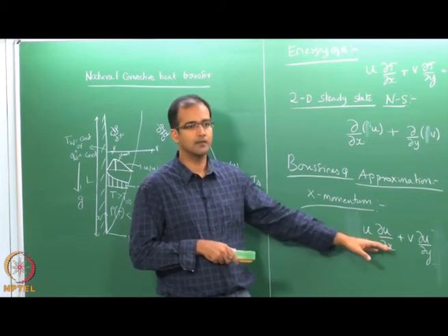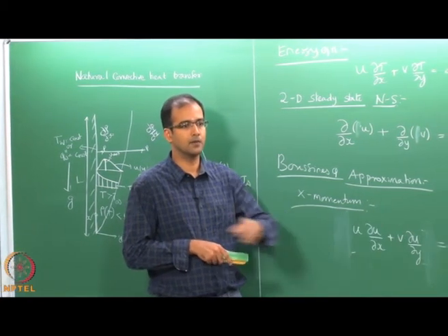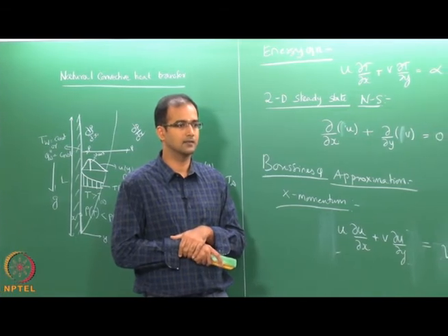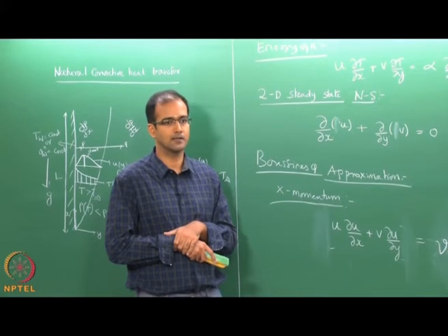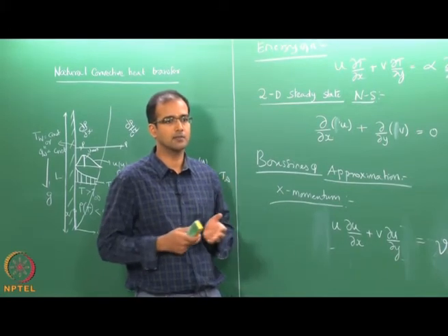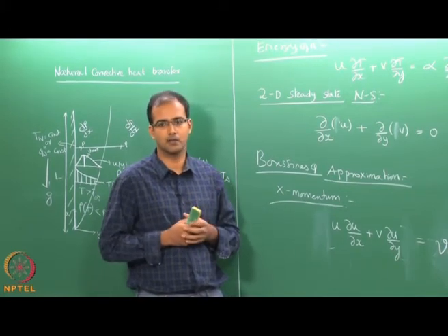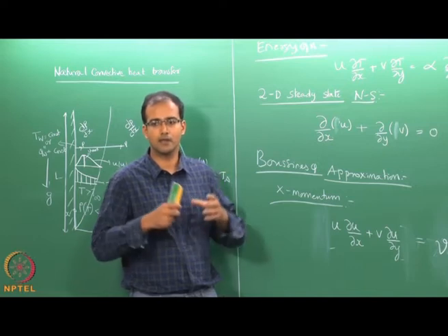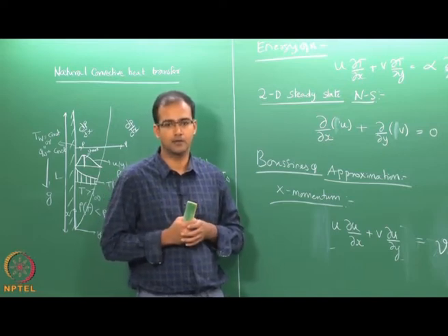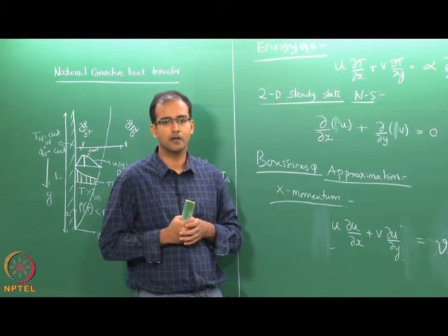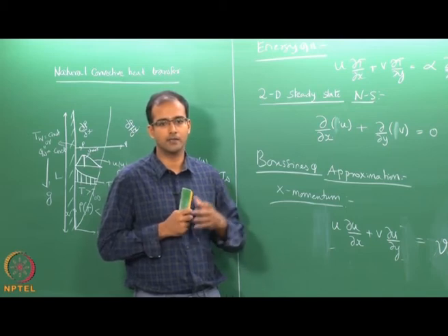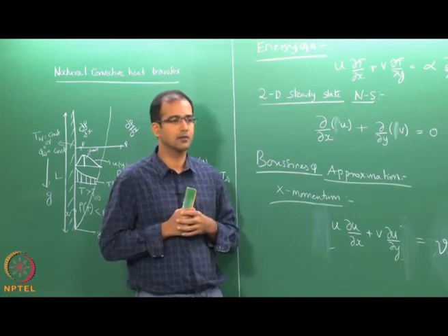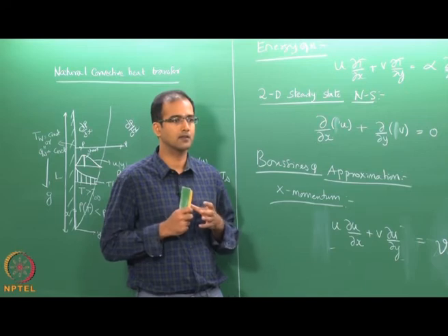But here the velocity profile itself is coming from the temperature. So, you cannot do it in a serial, sequential fashion. All of these have to be simultaneously coupled and solved. This is where the complication comes. You cannot find a simple sequential, segregated solution unlike the case of external forced convection. So, you have to couple all these equations and solve them.